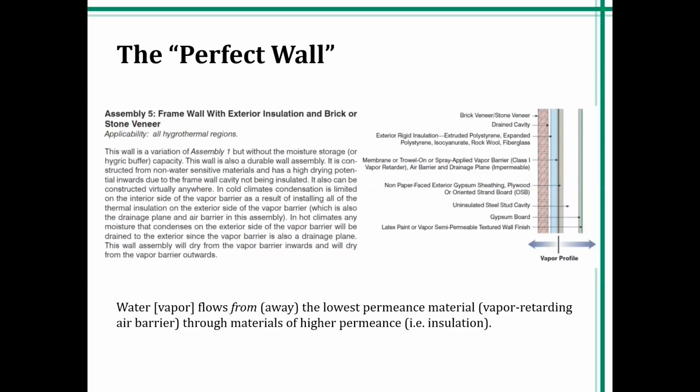As a rough industry average, the pink and the blue manufacturers of XPS insulation cite a water vapor permeance at 1.5 inches of about 0.8 perms. If we bump it up to 2, 2.5, or 3 inches, the permeance will not drop for every doubling of the thickness. It's a mathematical deduction, but we're still going to be largely in a class 2 vapor retarder category. So when we marry these two together, we effectively have now our entire environmental separation. This is far and away the most expensive wall when we place all the insulation on the outboard side, because now foundations naturally have to get deeper. We have longer tie mechanisms to reach through more insulation to attach the cladding.